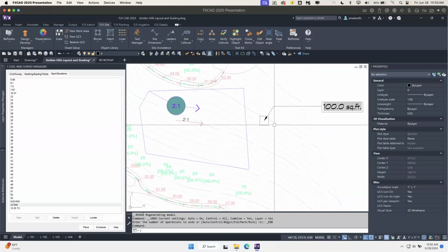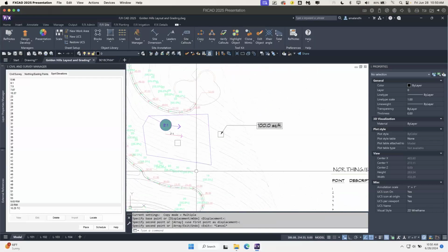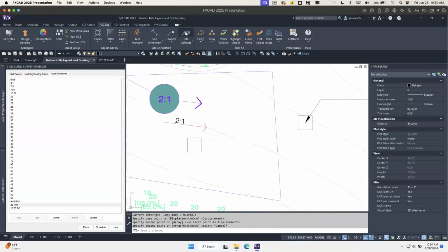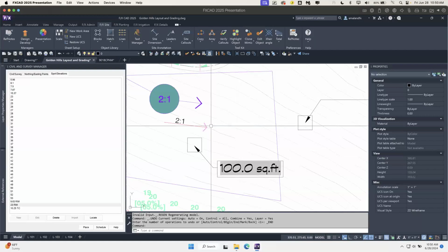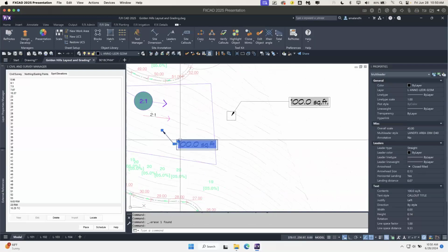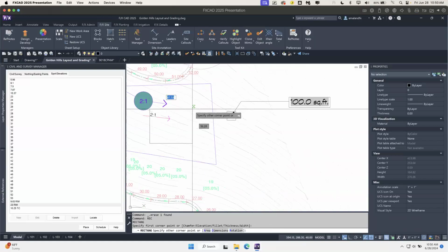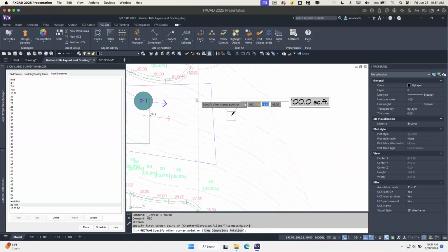If I copy this rectangle and put it over here, the area callout tool also works with this slope area. So if I were to area callout this one, it should have worked in here. It might be I chose too small of an area and actually rounded up. That's actually what happened. So let me go over here and do a rectangle, a slightly bigger rectangle. I'm used to meters. So let me go 100 by 100. That should show.